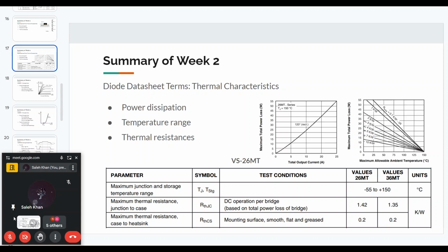The RDS versus temperature curve basically gives you how the RDS changes as the temperature of the junction changes. But it is not giving a limit. The limit is basically here. The curve that is provided will be given up to 150 degrees, and it will not go beyond that. But if the RDS is a particular value, then you can find the temperature based on RDS.